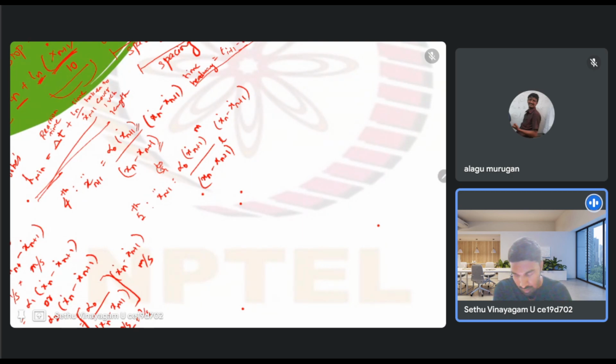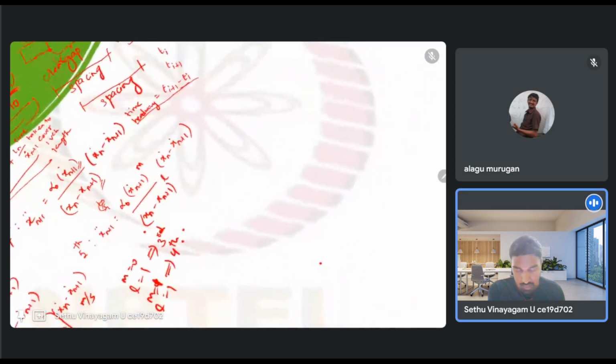For example, if you choose m is 0 and l is 1, you will get the third generation model, where only the spacing is there in the sensitivity, and the velocity of the follower is not there. Whereas if you take both equal to 1, m is equal to 1 and l is equal to 1, you will get the fourth generation model. So like this, you can have different models from the fifth generation model. Therefore, the fifth generation is a generalized car following model.